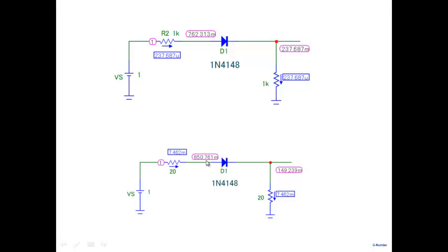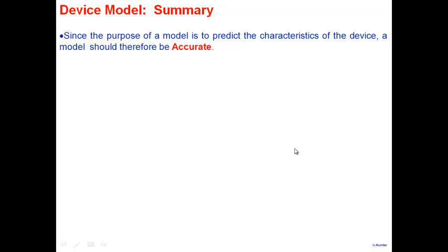So diode, we'll talk about it later. We keep on making an assumption that diode voltage is 0.7. To some extent it's true for certain cases, but for many others it's not true. Right? So look at the difference. If I use the simple 0.7 model, I obtain, let's say, 1K. The 1K is giving me an inaccurate answer. The actual suitable value of resistor is only 20 ohms. 20 ohms here and 20 ohms here. Of course, a design doesn't mean that there's a unique answer. You could get this 0.15 volt in other ways also. Okay, so often there are multiple answers to a problem.